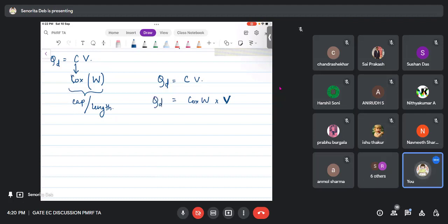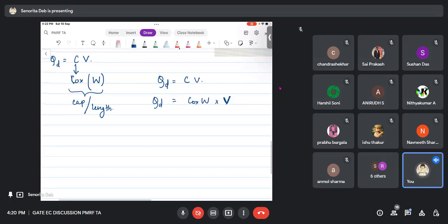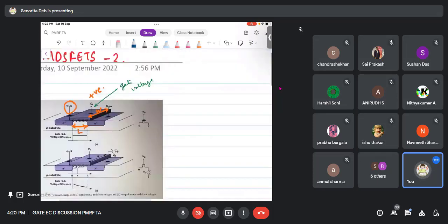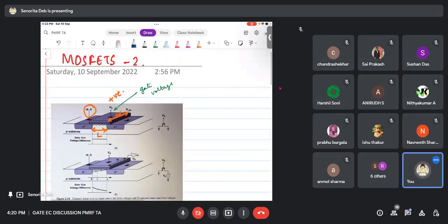Because of which voltage has this charge come? Because of the VGS that we had put, right? So we had put a VG here, and everything will be with respect to source, let's say. So VGS. And when VGS goes over the threshold VTH, then charge is coming.